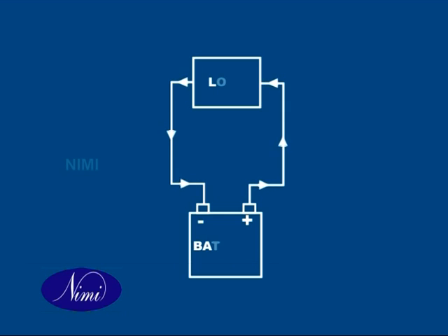Necessity of charging. During discharge, due to chemical reaction, the active electrodes become softer and the internal resistance becomes high, causing a low output. To reverse the action, send a DC current through the battery or cell in the opposite direction to that of the discharge. This process is called charging. The charging can be done through a battery charger. When the voltage of the cell falls to a certain level, the battery is said to be discharged and can no longer produce the rated flow of electric current.